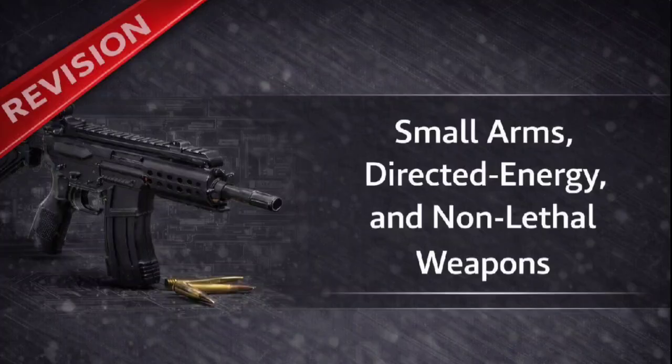Firstly, it requires a heavy breech block in all but the most specialized variants. And that big, heavy part moving back and forth results in highly inaccurate fire due to the movement and the vibration. It's unsuitable for long ranges, and, critically, it offers no means of adjusting power. You can't compensate for fouling, extreme cold, or poor ammunition. And the AFV problem. Yes. Because the breech opens immediately, it's completely unsuitable for use inside armored fighting vehicles due to the immediate release of toxic fumes into the crew compartment.